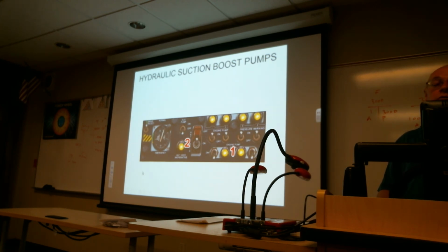That's called what type of reservoir? Bootstrap. Okay. You see a dotted box in a schematic around the components that indicates what? Power pack. Let's see, what else? You know that pumps do not create pressure. What do they create? Flow. And we create pressure by what means? Restriction or confinement. Very good.